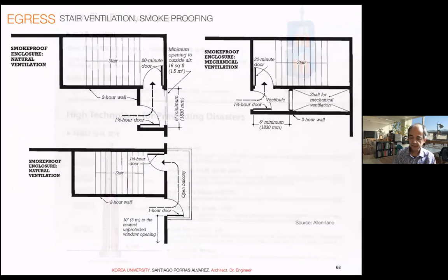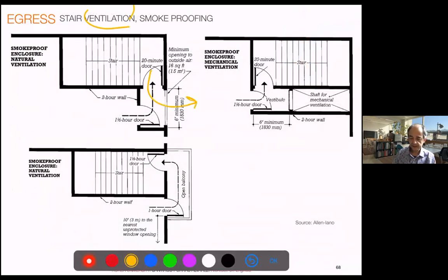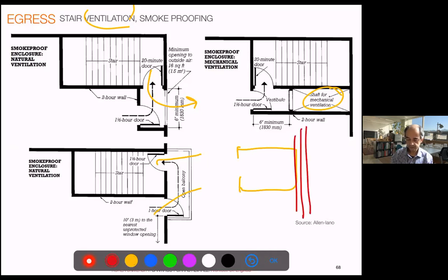Ventilation is important. The easiest is to have natural ventilation, right? That's great. Otherwise, you have shafts. Usually, if you have shafts on each of the floors, you will need, let's say, two shafts, or one on each side, right? One which gives you fresh air, and another which collects to the roof. So one is connected to the ground floor, another to the roof.